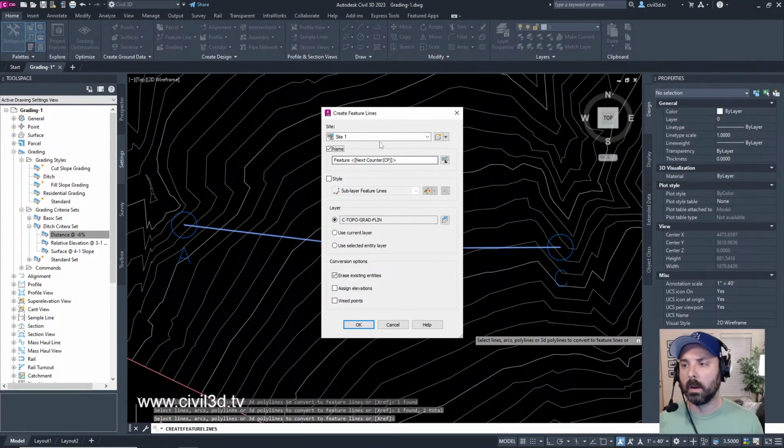That's where naming your feature lines can be very helpful, very important. For this exercise, you will assign names after the feature lines have been created, so we'll uncheck this box. We'll just leave it at its defaults. Following this workflow enables you to create many feature lines at the same time, but name only the most significant feature lines.